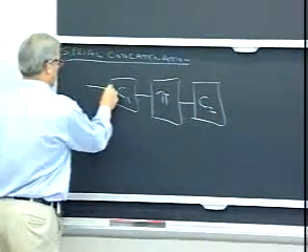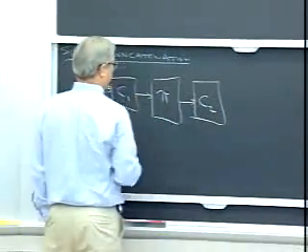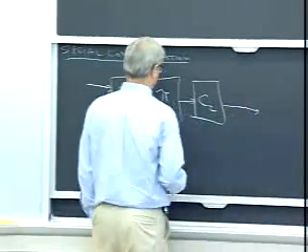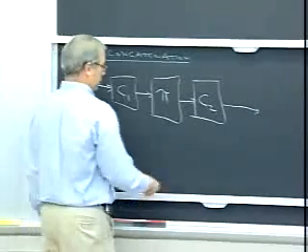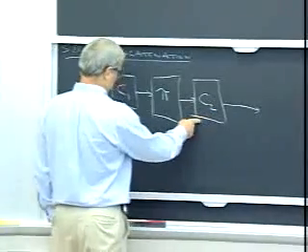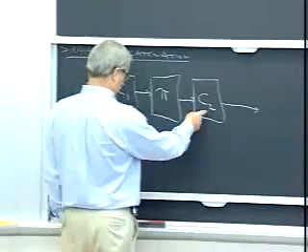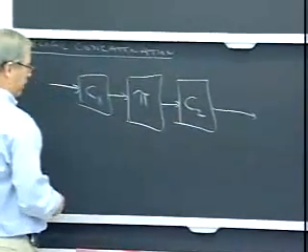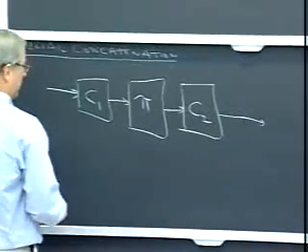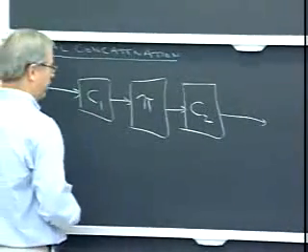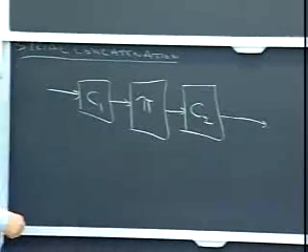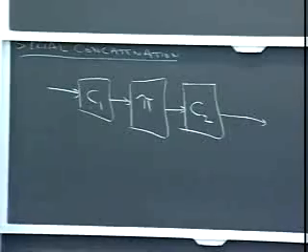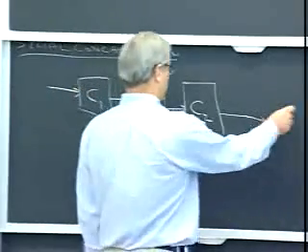This is the kind of setup that I talked about back when we talked about this could be a small block code or convolutional code that you do maximum likelihood decoding on, e.g. the Viterbi algorithm. And this could be a Reed-Solomon code, and the interleaver might be in there for some kind of burst protection or to decorrelate any memory in the channel out here.